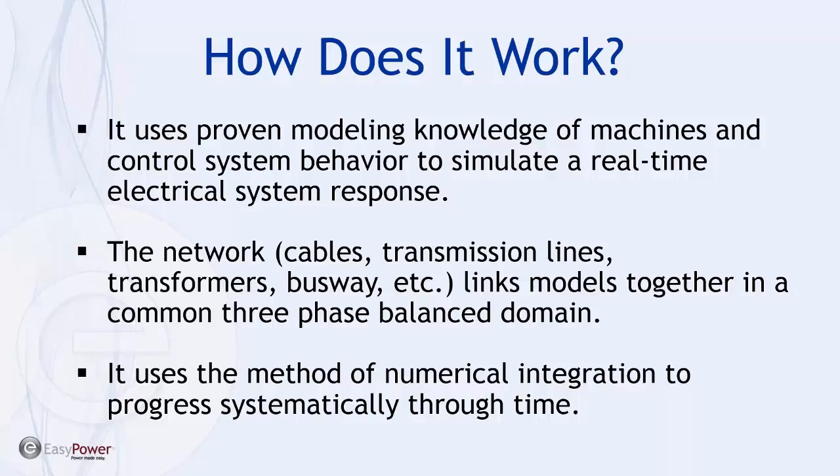So just note, EasyPower dynamic stability uses a positive sequence, balanced, three-phase simulation. We're actually not utilizing an unbalanced system at this time, at least not yet. And then finally, EasyPower dynamic stability uses a method of numerical integration to progress systematically through time to give us this real-time simulation.